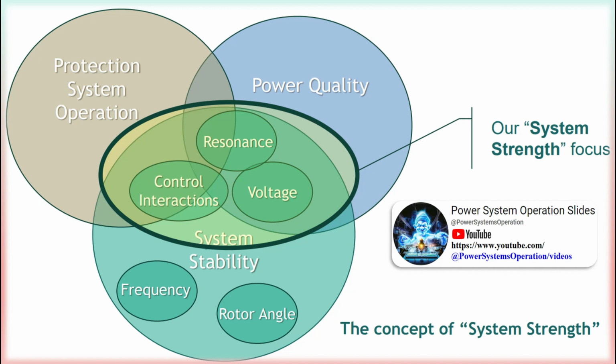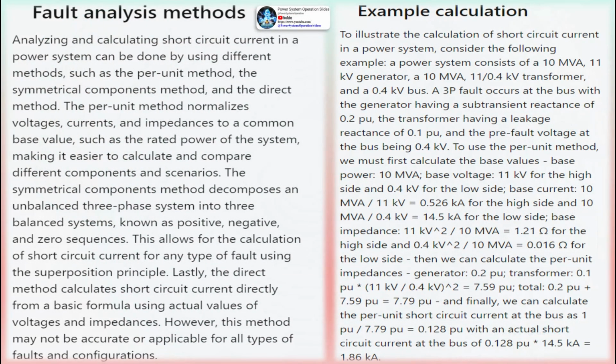No substation equipment can be installed without knowledge of the complete short-circuit values for the entire power distribution system. The short-circuit calculations must be maintained and periodically updated to protect the equipment and the lives. It is not safe to assume that new equipment is properly rated. The results of a short-circuit analysis are also used to selectively coordinate electrical protective devices.